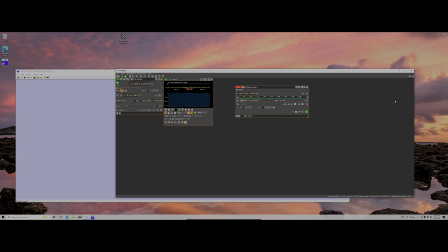I've recorded some live ELT transmissions using my HackRF while I was doing ELT tests on live aircraft. And I'm able to replay those with the HackRF into a direct couple for the RTL-SDR. The reason I've done this is basically for testing, so I didn't need to constantly be at a live aircraft or constantly be setting off ELTs to troubleshoot and to try and get this up and running.